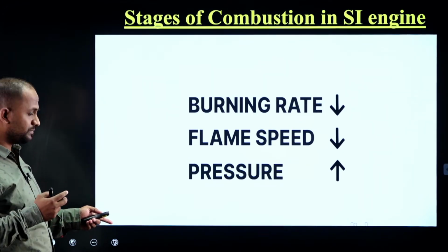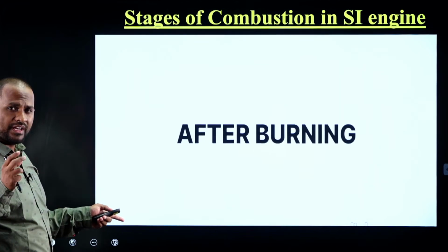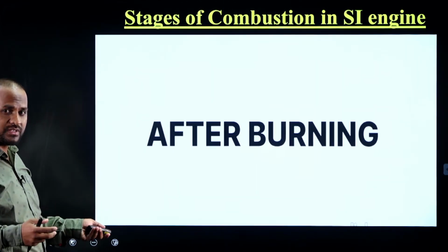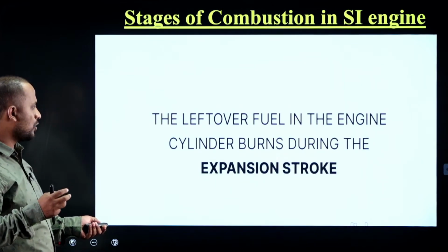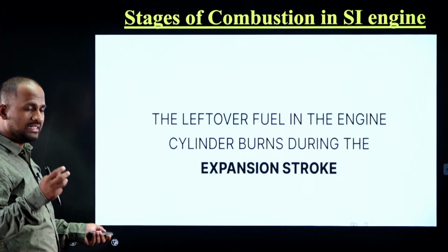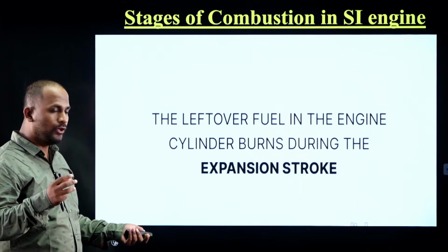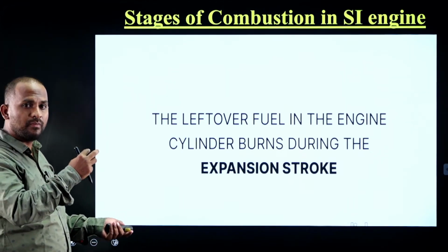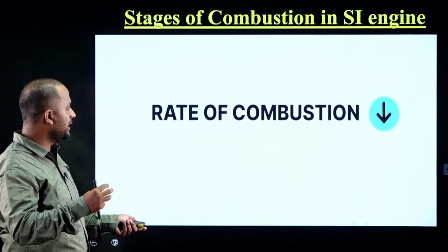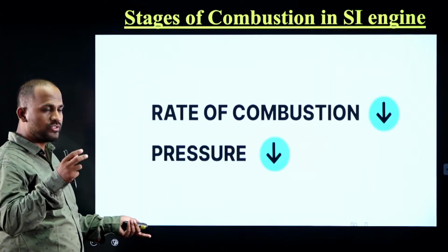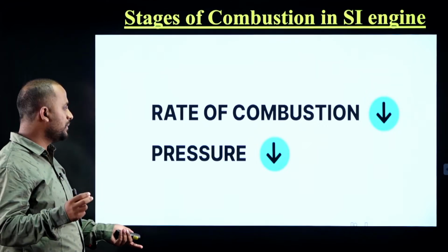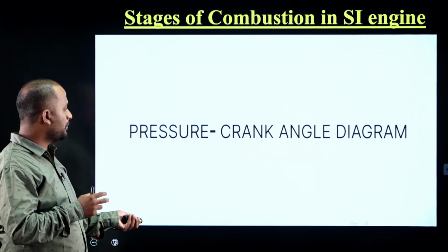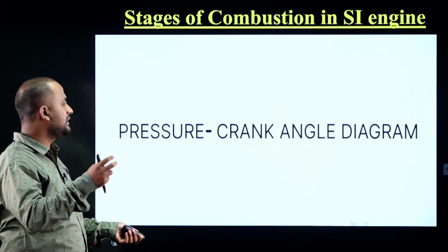After this, the next stage is the after burning stage. What happens in the after burning stage? The leftover or unburned fuel particles in the cylinder are burned during the expansion stroke, while the piston travels from TDC to BDC. In this stage, the rate of combustion is low and the pressure is also low because of the fewer fuel particles present. Now let us see the pressure crank angle diagram.